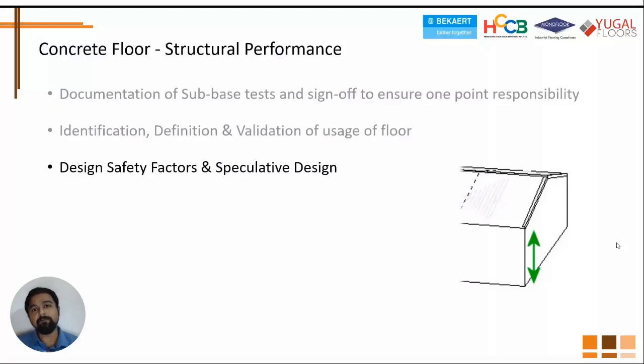And in some cases, you don't have the loads that you are going to expect. So some details, like shown in the picture, like the clear height of the building, can give you a fair indication of the maximum height of racks that you may be expecting on the floor. So you can speculatively design using the maximum height of racks that you are expecting in your building, so that you will have a floor of sufficient structural performance. And the design factors also need to be kept in mind when designing.